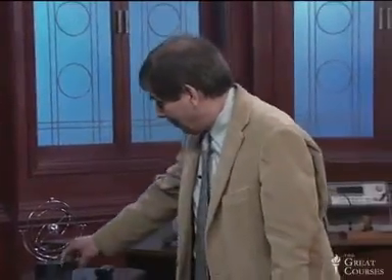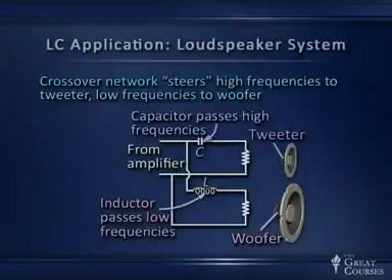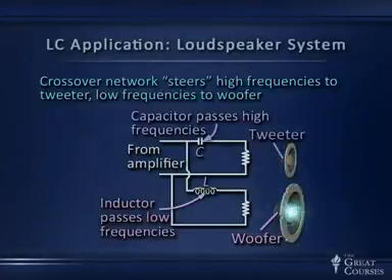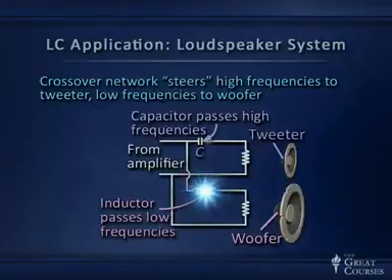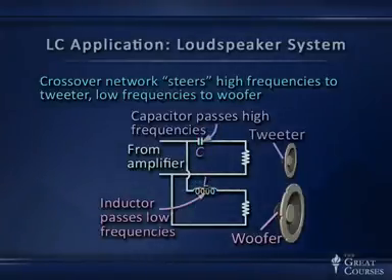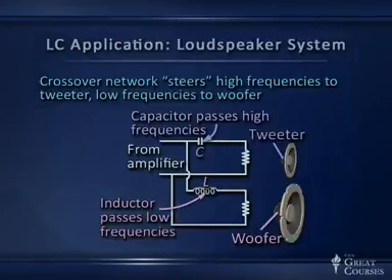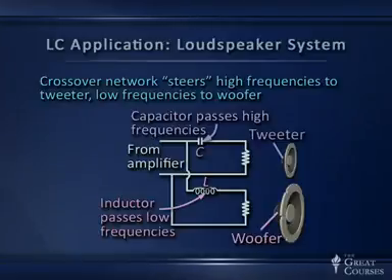Now let's look at a few more applications of this idea of resonance in LC circuits. Here's another example. This is the crossover network in a loudspeaker system. In any good loudspeaker system, there are at least two separate loudspeakers. One a tweeter for high frequencies, one a woofer for low frequencies. Sometimes there's a mid-range as well. We use inductors and capacitors to steer the low frequencies to the woofer and the high frequencies to the tweeter, so we don't waste low frequency power trying to drive the tweeter and high frequency trying to drive the woofer.